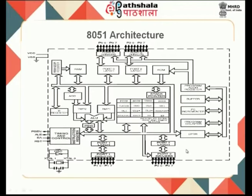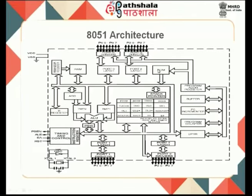And we will have special registers. I can call this DPTR, which is interfacing the memory address for the external memory. Sometimes we will not be using only the RAM and ROM. If this is not sufficient, we will be using external memory. That particular external memory is accessed through this DPTR. The memory address will be sent through this DPTR, because the DPTR has a 16 bit address. So, 2 registers are combined together.